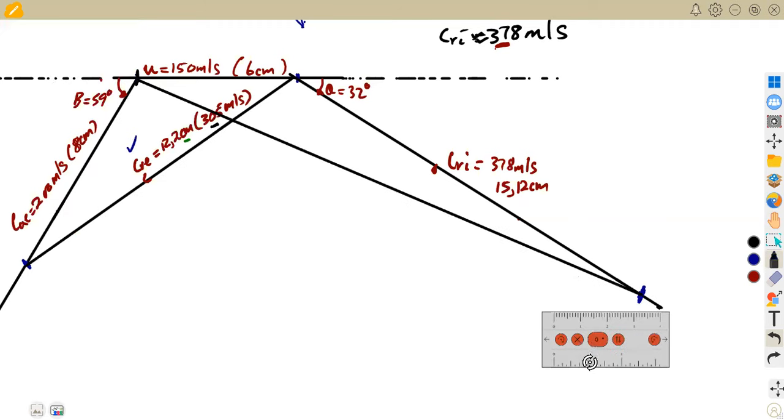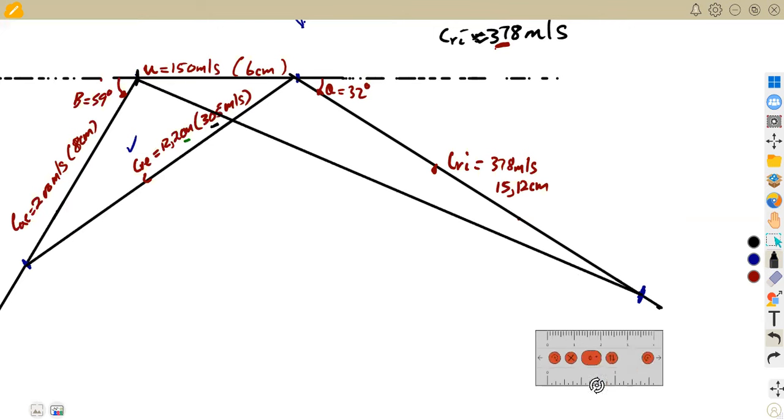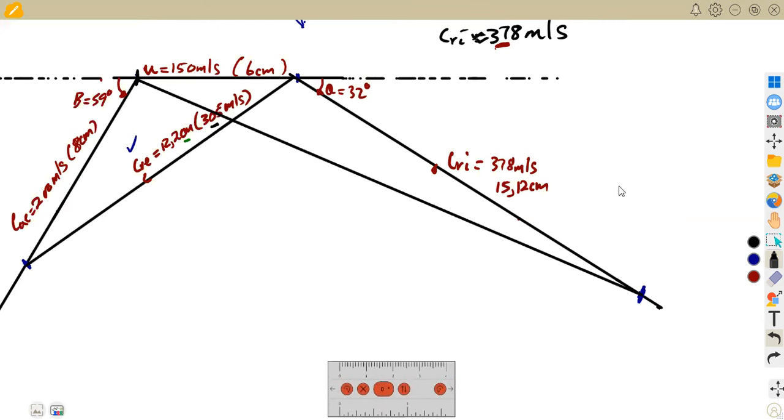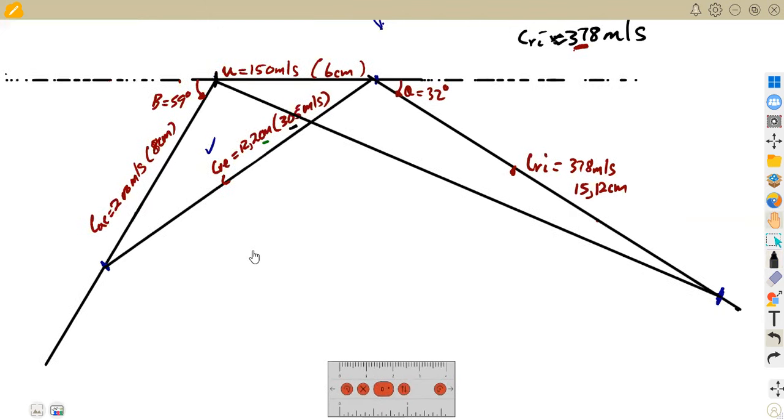All right, so in this case, I'm saying I've completed my diagram, but after also completing your diagram, try to represent all the velocities, make sure they are there. So as we can check, we do not have this velocity, which is the absolute inlet velocity of the gas in this case. So you're going to measure. Like I said, guys, you place your ruler from this point up to this point. If you were to measure properly, this was going to give you 20.5 centimeters.